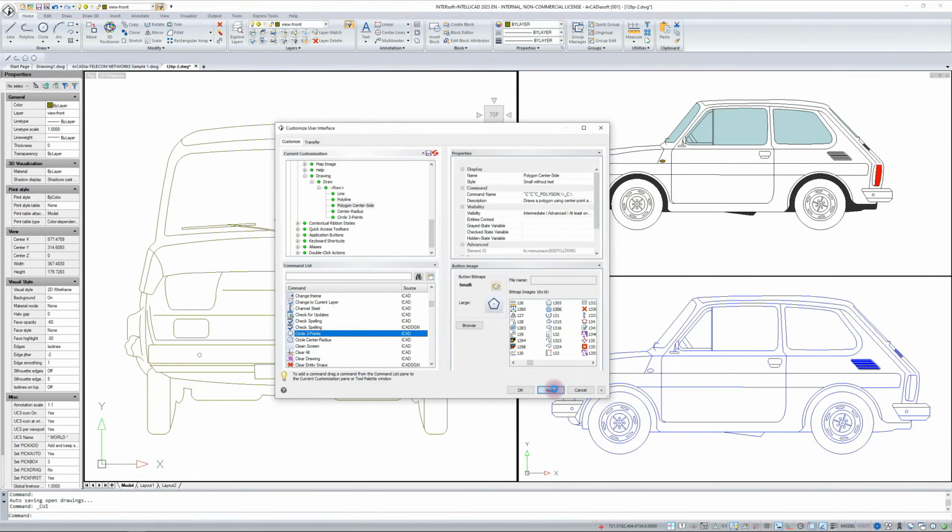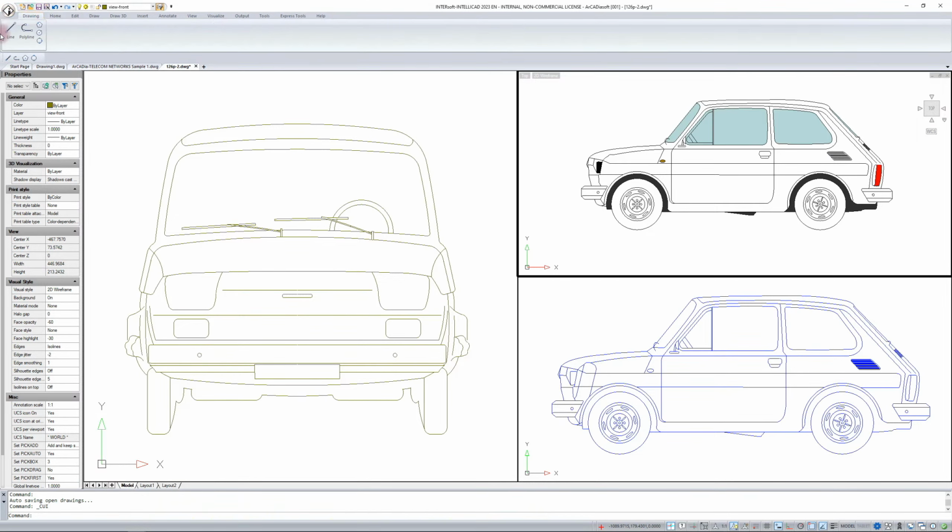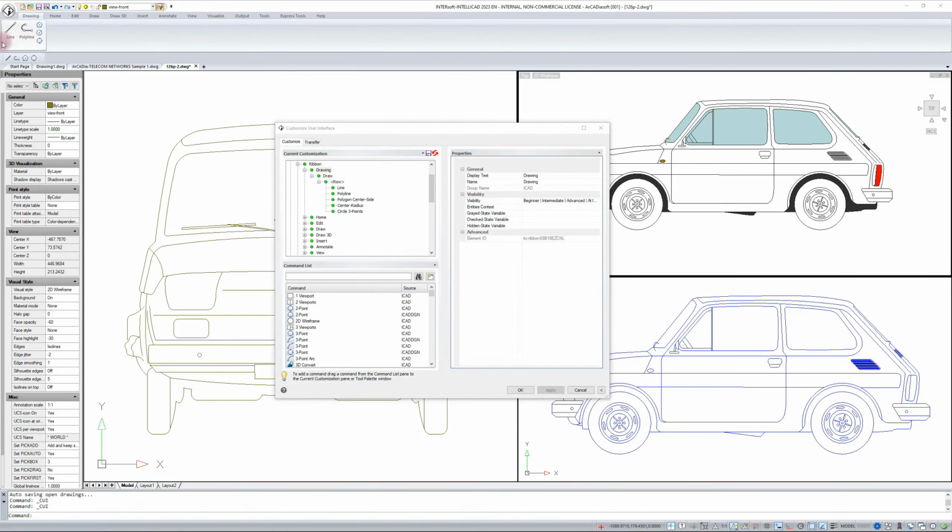I'm already clicking apply. Well, we've already turned on the ribbon. We can see in real time what it looks like and whether we introduced everything correctly. And now we can create more of these panels. We go into the Customize window again. But I see that our ribbon does not have a name on the panel, that is, this logical group. Please see that there's no caption at the bottom. Here I have to add it. Now we will apply, and you can already see the panel name.